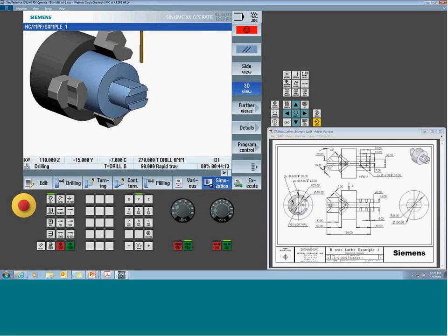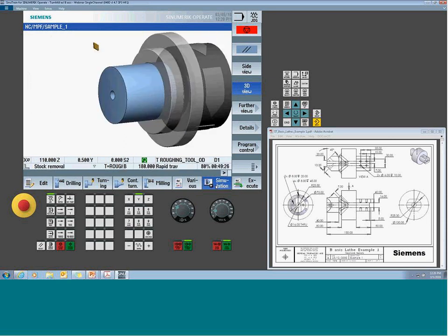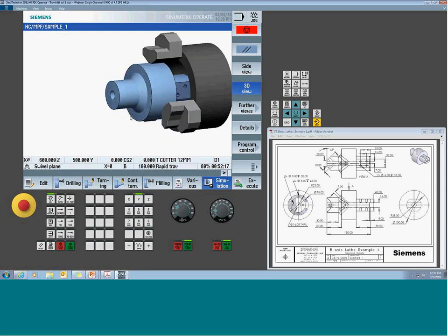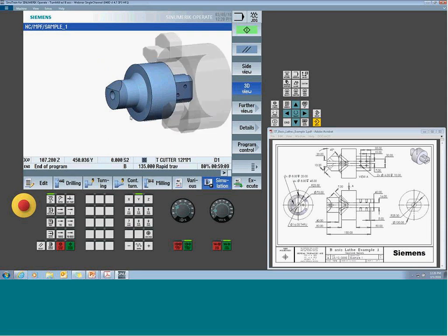All right, so it just transferred. I just drilled. Okay, so now we're on the back side. We're turning to get our swiveling tool. All one cut. Obviously, you would probably do this in a couple of passes. Here I see the feature, just like I see on my print, is off 90 degrees from these flats. So I wanted it. So my C0 was a good strategy.